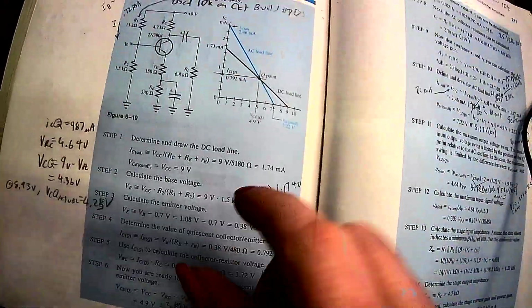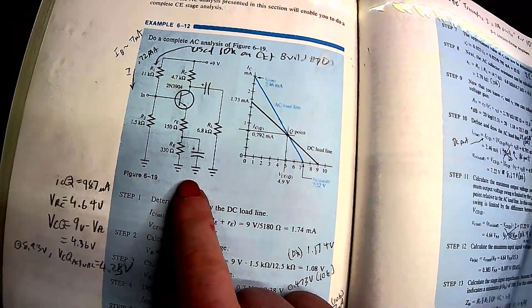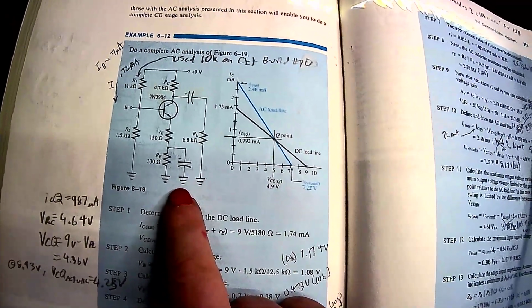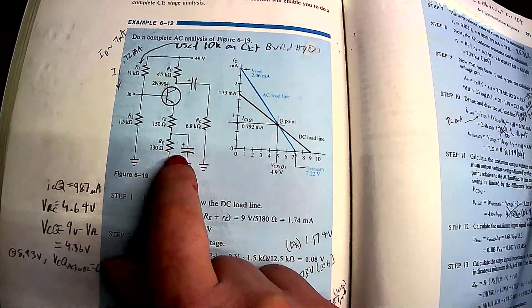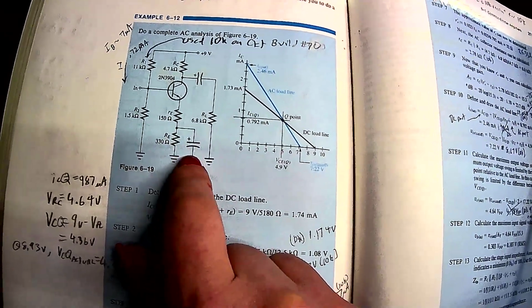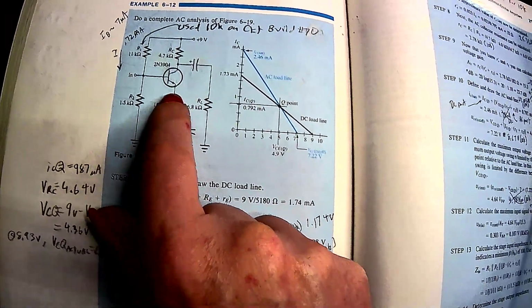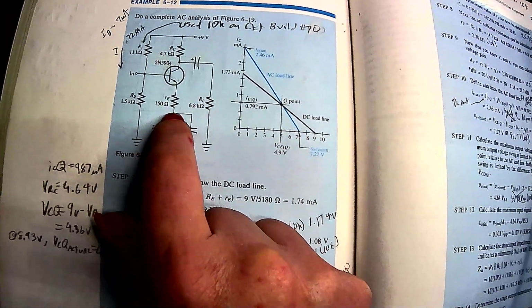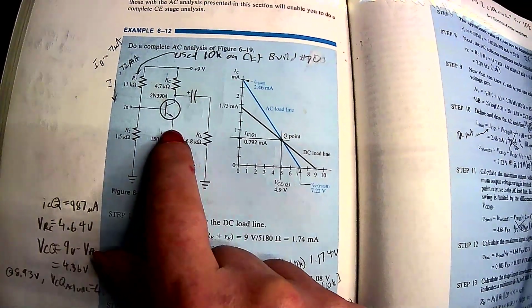If you take this one for example, I did actually build and test this circuit. Like I said, they've got a split arrangement here, bypassing most of the biasing resistance, but using some of this for gain stabilization, and it's like degenerative feedback.